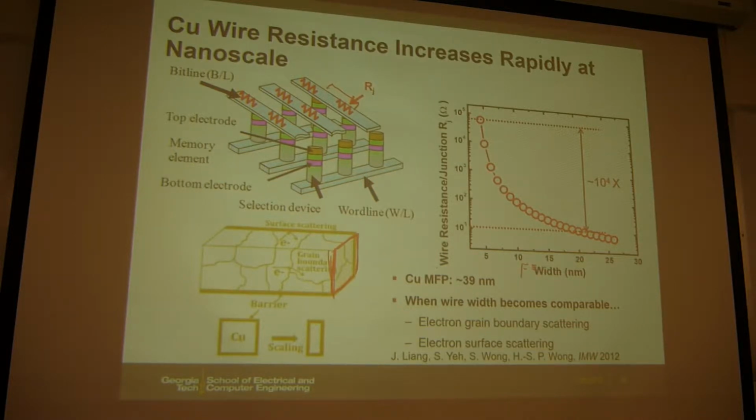What you need to do is look at the ITRS table we provided in the homework to find the resistivity as a function of the technology node. Then you need to calculate the resistance per segment. For example, here you may have one segment.